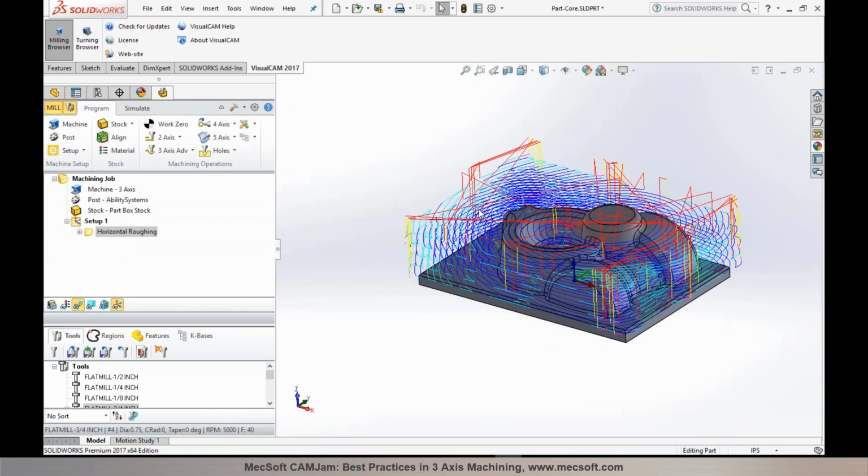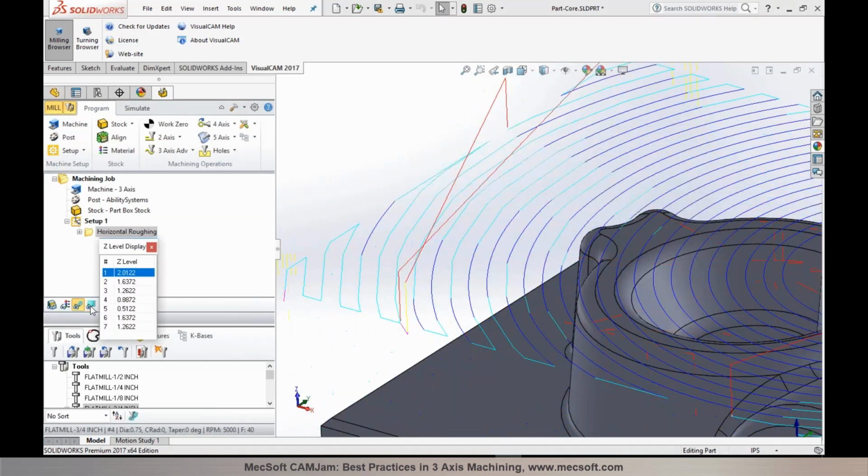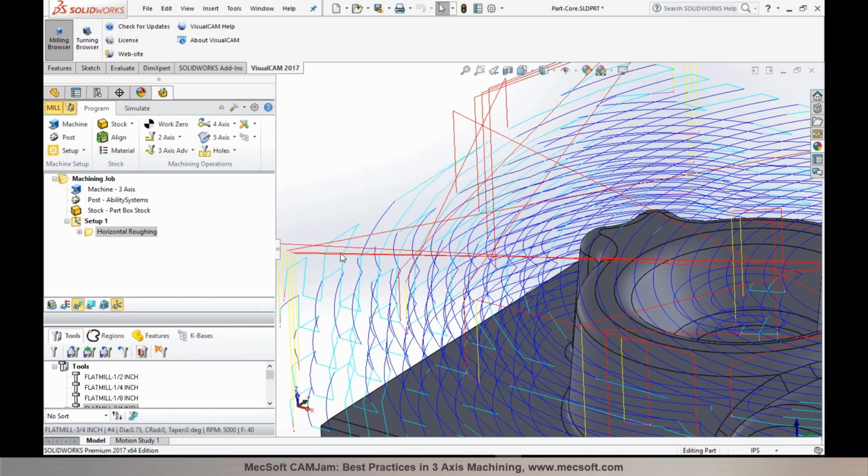Now you might be wondering what arc fitting is and how it affects things. As you take a look at these toolpaths, these arcs are being fitted to the linear motions that are generated on the toolpath. So for best arc fit results, you'd want to set the arc fitting tolerance to be 2 times your global tolerance. Setting the arc fitting tolerance much slacker than the global tolerance could cause the arcs to deviate from the actual geometry. So as a general practice, and best practice, you would want to set the arc fitting tolerance to be 2 times your global tolerance.